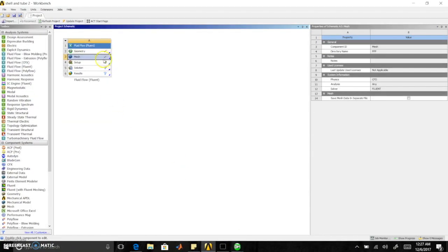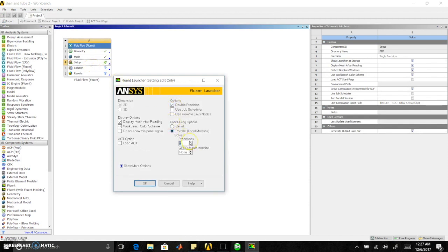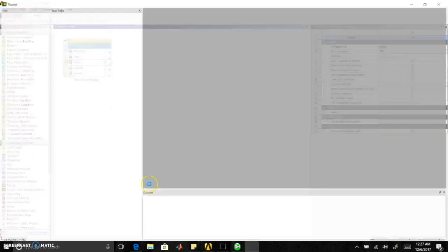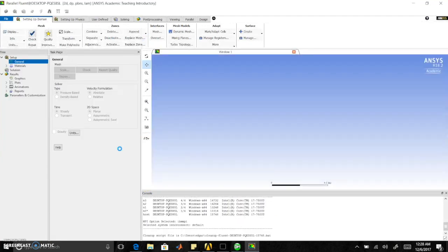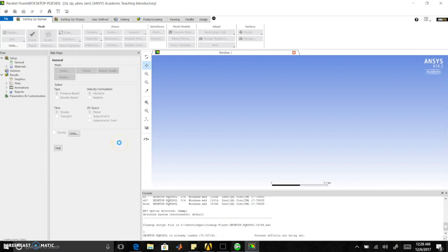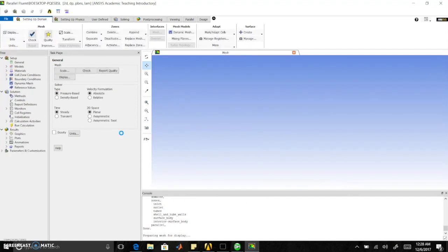So going back to the dialog box of your Ansys study, we're going to go to Solutions, click double precision, parallel, and choose 4 processors if you have a quad-core processor. Any other processor, you might need to choose less. So I'm just waiting for the mesh to load because it might take a while if it's very fine. You'll get some errors if anything is wrong with it. You might need to go back and change your mesh.